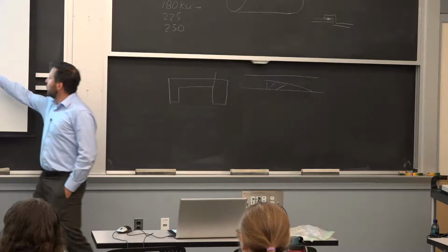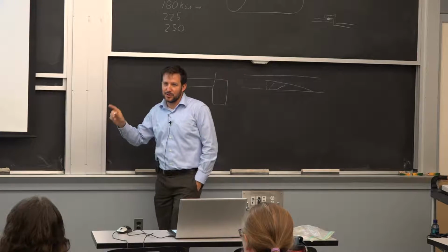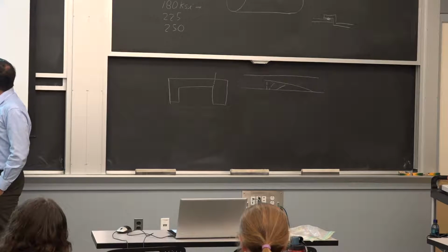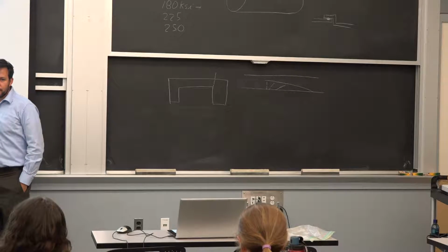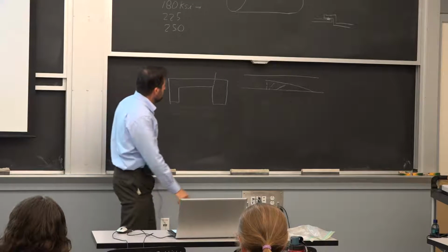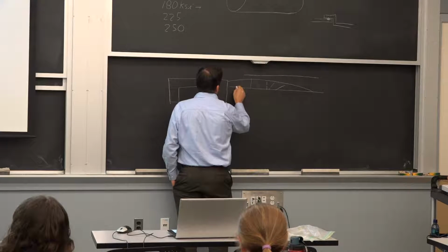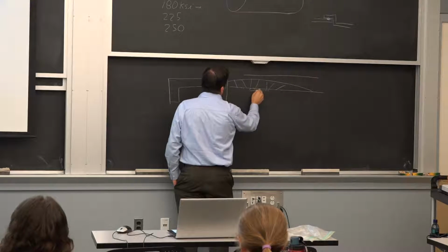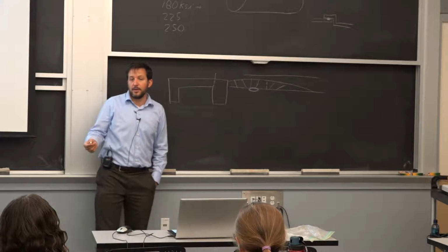From that vantage point, they had already cut it up, by the way, so it was always more fun to figure out what's going on. But by this general shape, I know my initiation is this way. So there was a pre-crack before reaching the critical strength of the material. And right over here is where I went to look: do I have an inclusion?